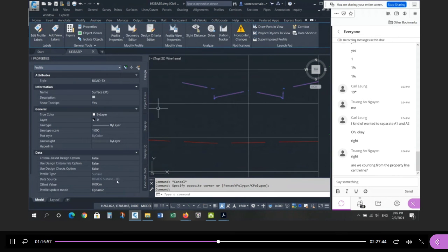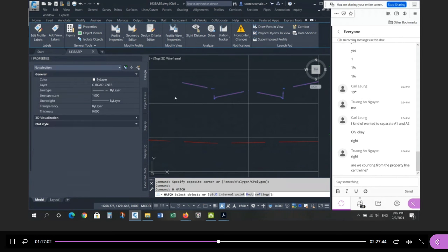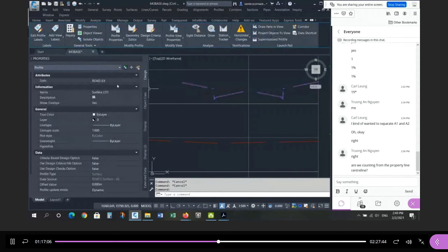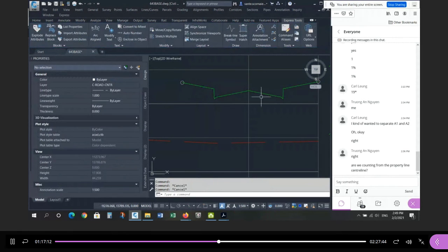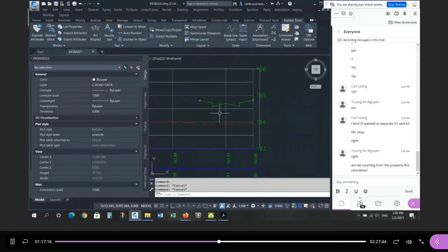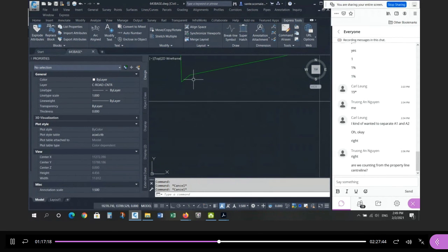Let me just change the style. Style for this. We'll use, oops, instead of road X, let's make it look like even proposed. Right, so you can see the full cross section of the road. So that's why we build the corridor. So now I have the starting condition.